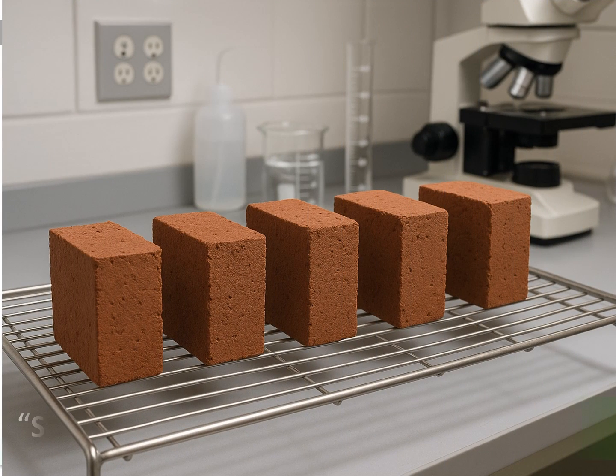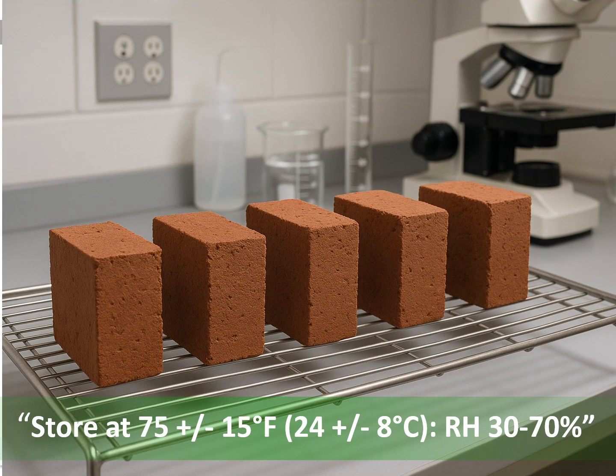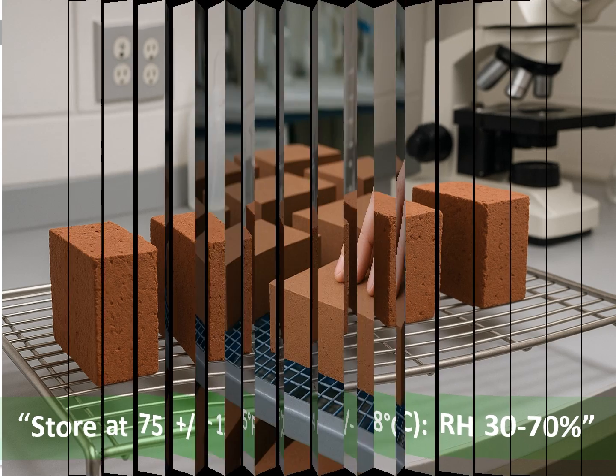After drying, samples shall be maintained in a drying room at a temperature of 75 plus or minus 15 degrees Fahrenheit, 24 plus or minus 8 degrees Celsius, with a relative humidity between 30 and 70%. Store the units free from drafts, unstacked, with separate space for each specimen.